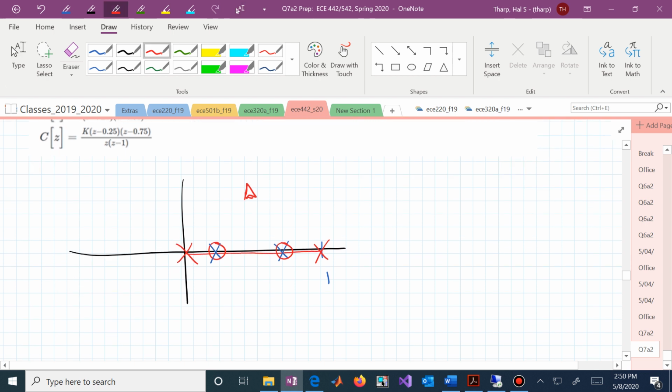We want to know what's the gain to get us to that particular triangle, and we know that triangle belongs to the root locus because, really, with our glasses on, those pole-zero cancellations, which are allowed because they're inside the unit circle, we don't even need to focus on. We now have our root locus going through 1/2 plus and minus j1/2.